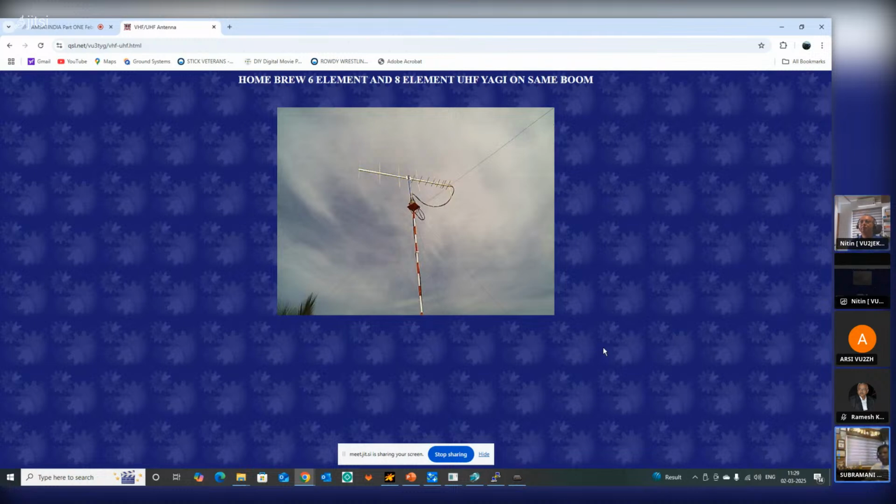Yeah, you're right. As of now, none of the amateur radio satellites can even think of going for a phased array antenna. But we have phased array antennas for synthetic aperture radars, where you can electronically steer the beams rather than having a mechanical system. You have multiple antennas mounted on a dome, and you can change the phases and steer the antenna pattern, the beams. This is a little bit complex, but compared to the mechanical way of steering the antenna, this is always preferred. Over. Okay, thank you, Shripal.